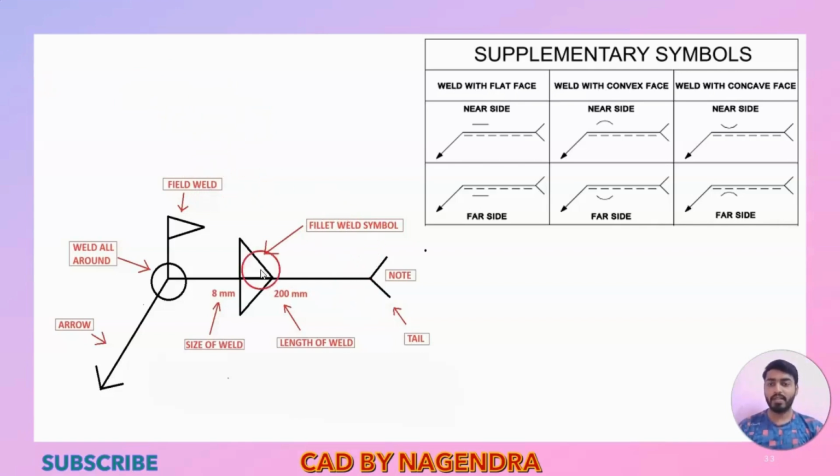Then the fillet weld symbol. Here we need to mention which type of welding we need to do. Like we have seen before in the weld symbols, whichever type we want, we just need to mention the weld symbol here, then the size of the weld, then the length of the weld, how much length we need to do, then the tail will be there. So like this we need to mention the welding symbol with specification. Again we'll be having supplementary symbols here.